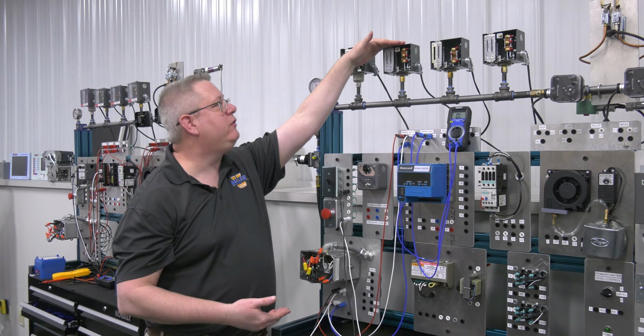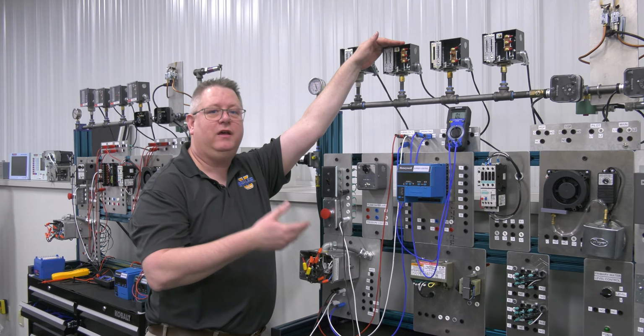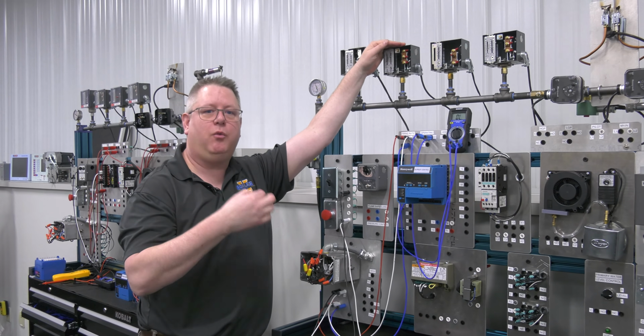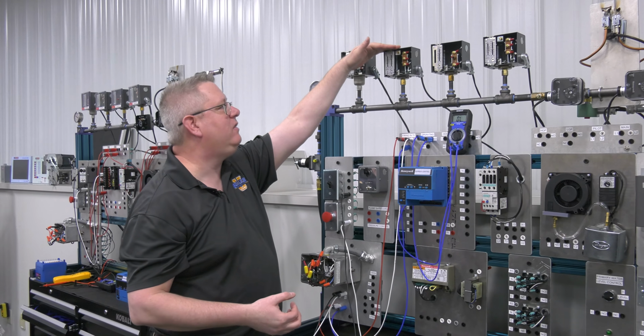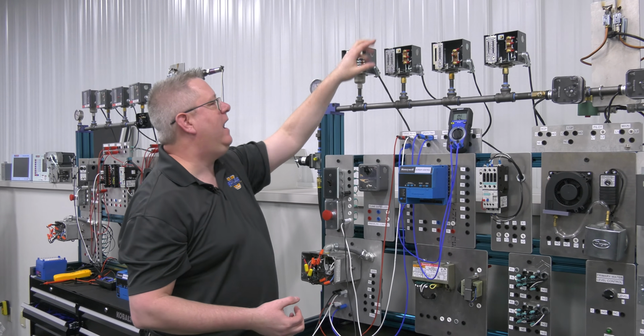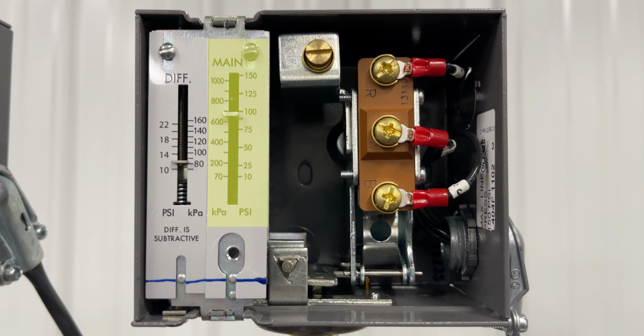So our operating control, what is it doing then? It's actually our first high pressure cutout. We're turning the boiler off when we attain the pressure setting on our operating control. And we have a main setting which should be at or approximately at that cutoff point. So if I set this for 100 PSI, you would reasonably expect it to shut off at 100 PSI, but it's going to be in the vicinity.